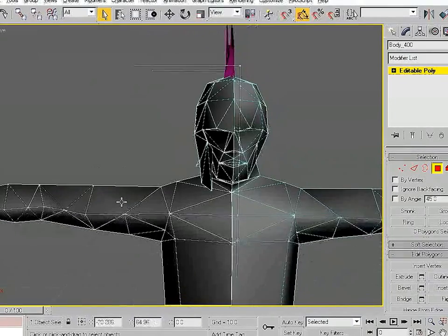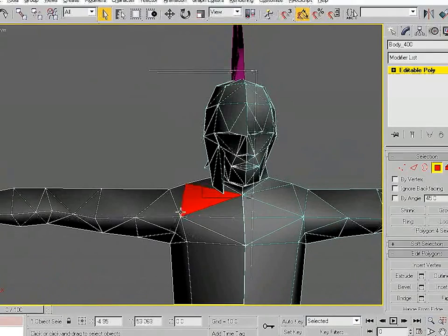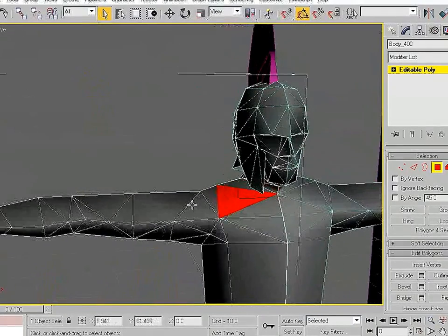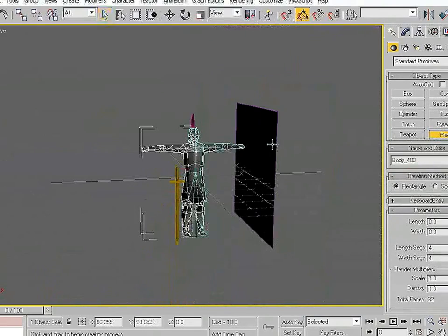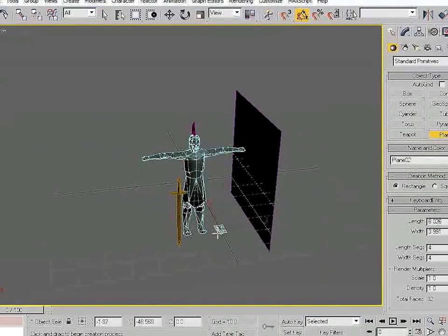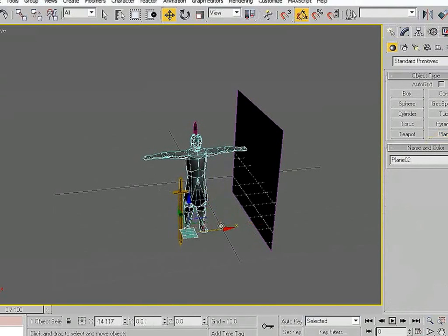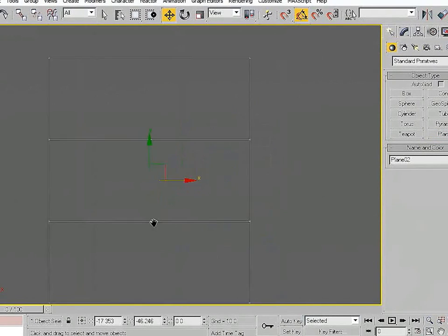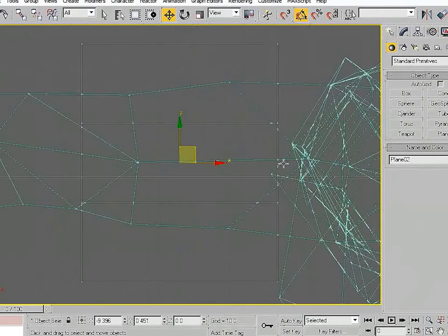And there are a couple ways to do this. I'm going to start with a new plane actually. You could have selected a loop around the arm and extruded it. Well, I'm going to start with the plane. Separate 3 ways lengthwise, so you can bend it around the arm.